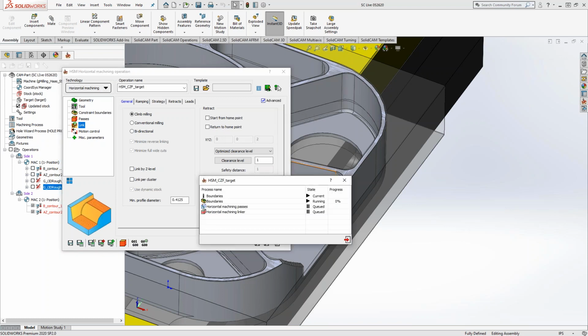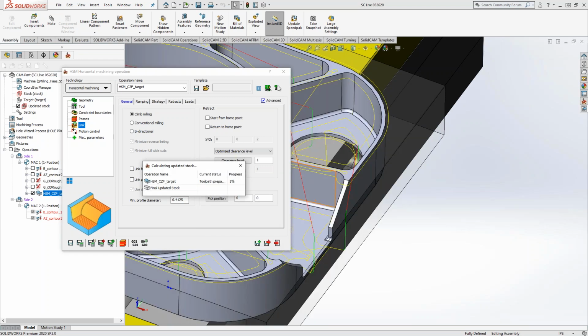You can just go in there and modify it if you're looking to really fine tune that tool path and get everything looking the exact way that you would like it. Absolutely. So doing the horizontal machining calculation here, and I didn't give it any wall offsets, so it will also finish the wall, very much like what Kevin was mentioning. And I probably should reduce the Z top a little bit because it's actually doing the top face as well. So we'll take that off.